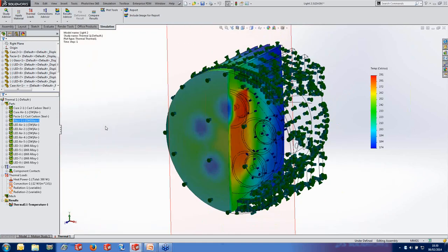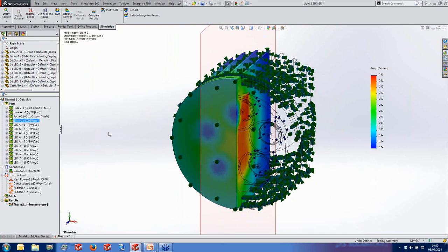So we can see very quickly with SolidWorks thermal simulation that we can test design ideas and potentially improve designs very quickly. I can now go back in, model up some different fins, come back in, and simulate it. The simulation for this one takes approximately 1.5 minutes, the same as the other one, because there are no fillets on it. But we can test new design ideas for cooling methods for LED lamps very quickly without having to make any up, do some testing, go back, and try again, because although these would be cast in the end, we're unlikely to cast them for the first off prototypes.